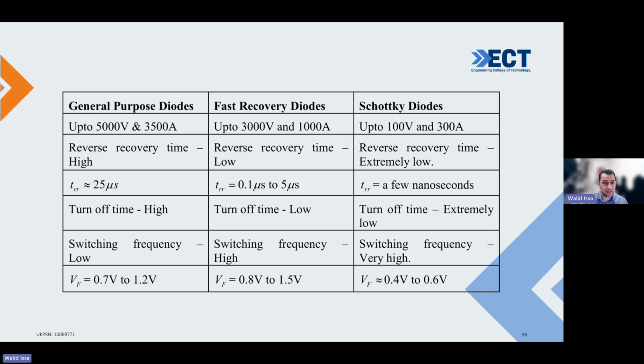And these are some small comparisons, because we have three types of diodes: general diode, fast recovery diode, and Schottky diode. Fast recovery diode is the best for everything, okay, but it might not really be useful for every application. Schottky diode is good in fast recovery time. It doesn't have any recovery time, but unfortunately, I can't use it for any application over 100 volt or 200 volt. I can't use it for application 400 volt or 1000 volt. Which one can I use? Fast recovery diode. Okay, so you have to make a small self-learning activity to know and to ask these questions.